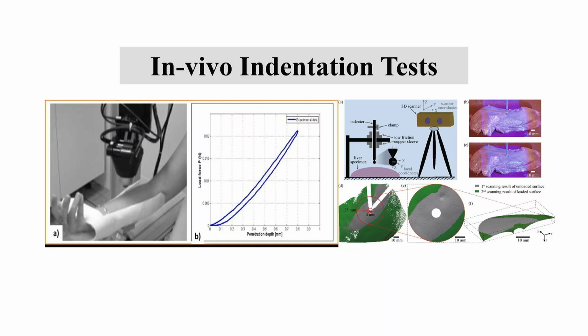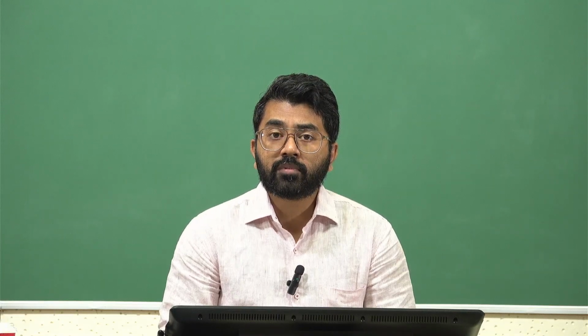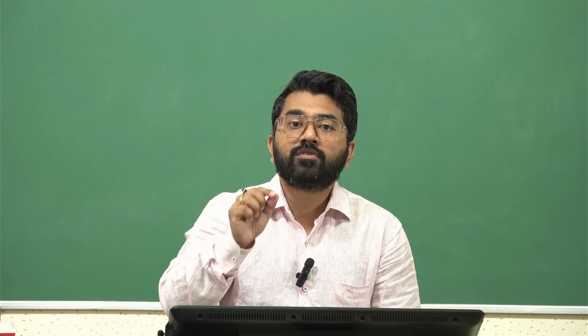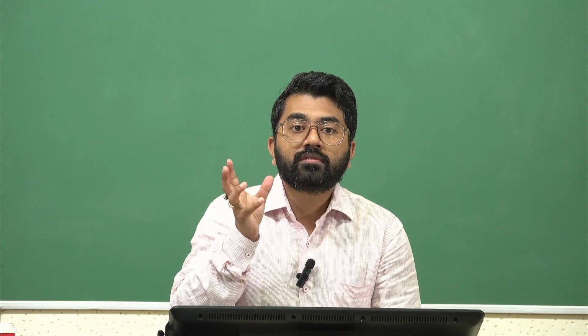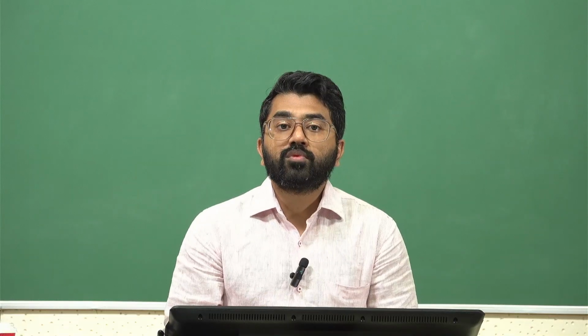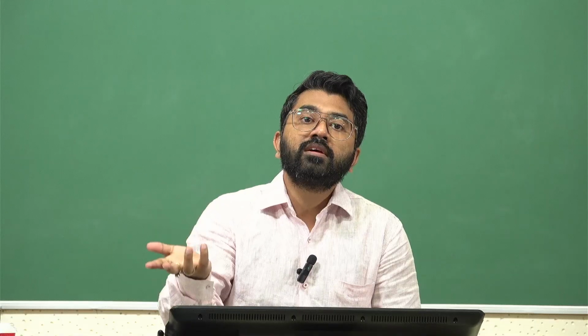The head of the indenter is of interest, because that's something which is designed in a particular way. You cannot just have a v-shaped indenter or a certain round shape indenter. It is well calculated what the circumference would be, what the radius would be, and whatnot, of the indenter, and as per that you are predicting a certain type of test.